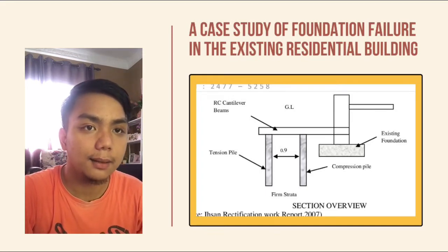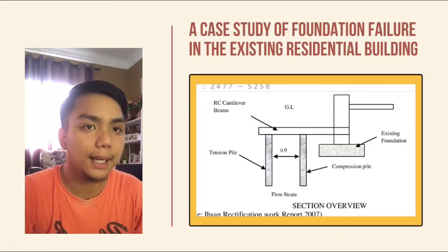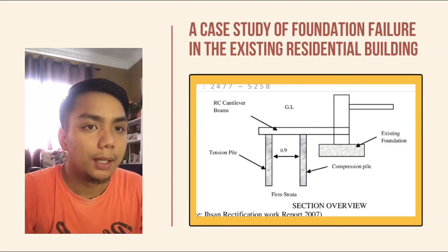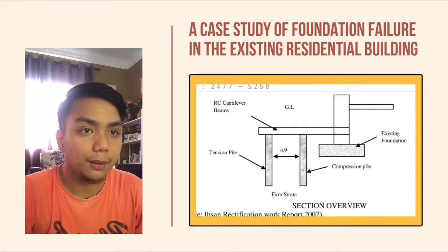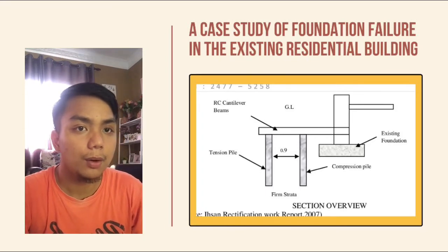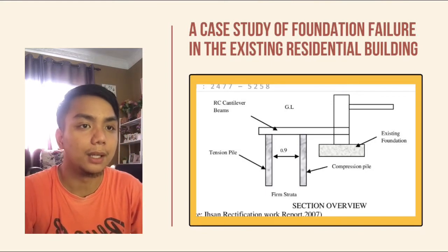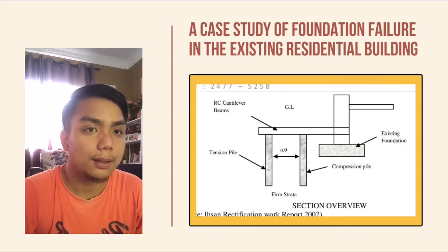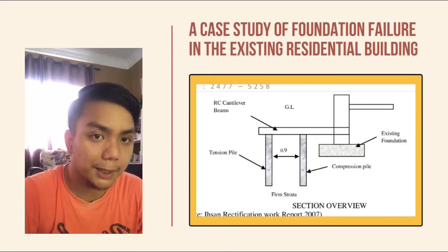First summary. This study concludes that it is recommended to perform human reliability analysis in slope construction to reduce the chance of error holistically. The finding also confirmed that whether the safety factor of the slope is high or low, there is always possibility of instability if the probability of failure due to human uncertainties is not taken in a logical manner.